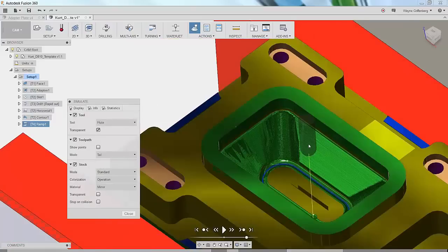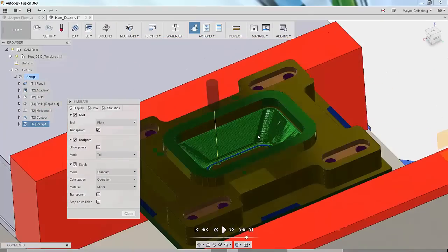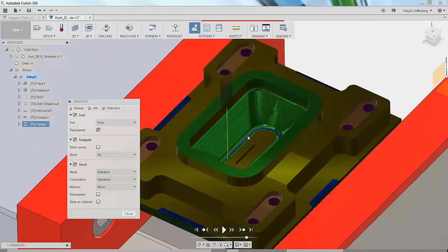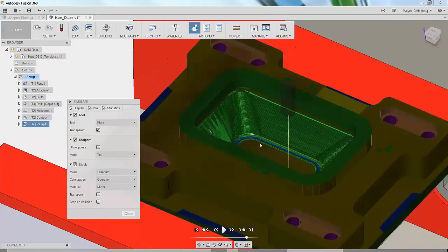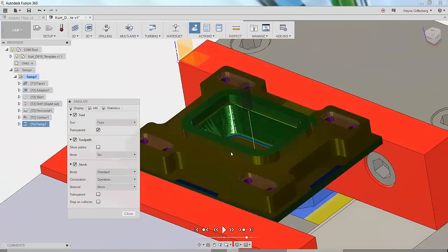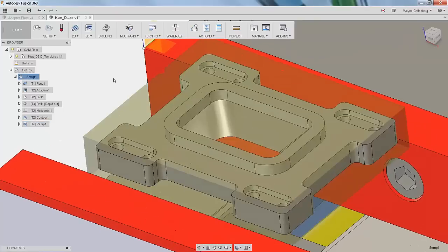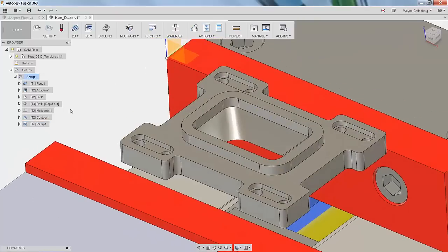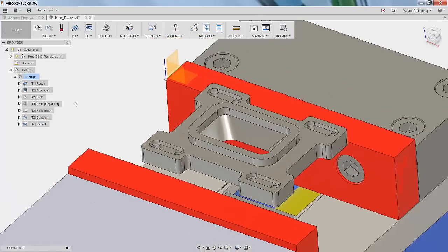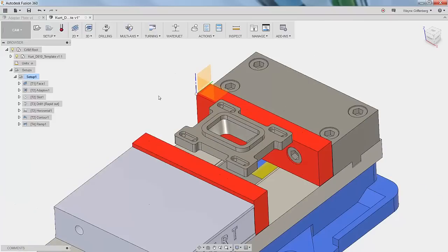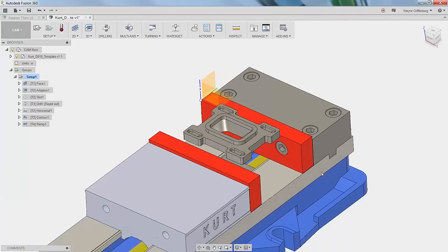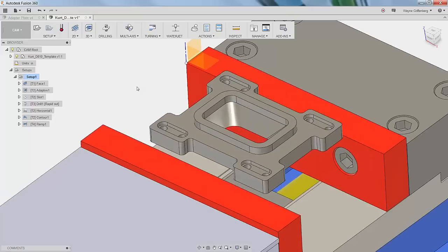But that's a ramp, and you could try different toolpaths, but that'll rough it out, or at least that'll get it finished. But I would really dial in to get those cusps really low. So that's being able to get some of the 3D toolpaths onto the part. And so we were able to walk through, I drew up a part from scratch, walk through that. We're able to download, upload, and be able to make an assembly out of a part, SolidWorks part.